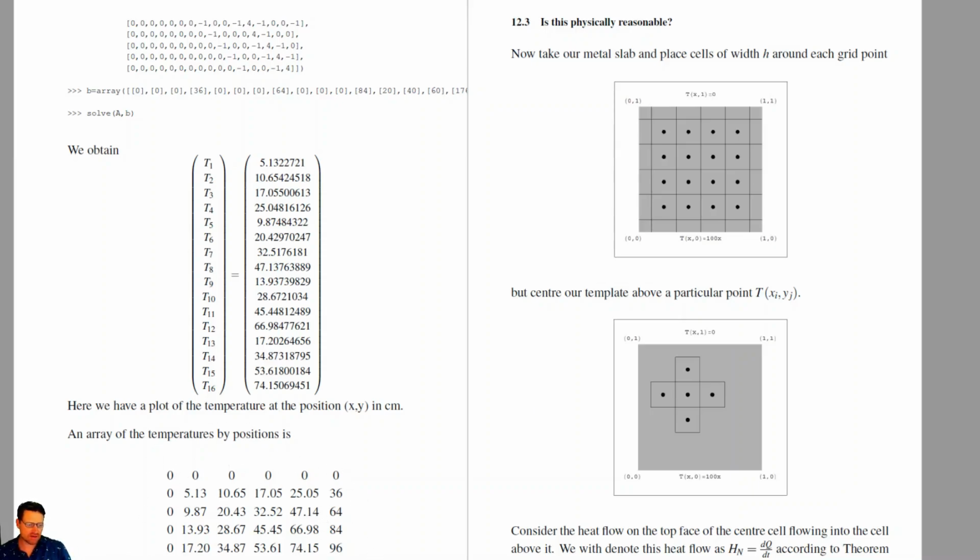So you can see I've got 0 along the boundary, as we said earlier. The bottom, we got 20, 40, 60, 80, 100 as given by the boundary conditions, and the same on this right hand side. But what we've done is we have now solved using this numerical approach for the interior temperature values, right? And you can see it does look like it matches up with the boundary conditions. All right, so that's the technique, and it's a very simple technique.